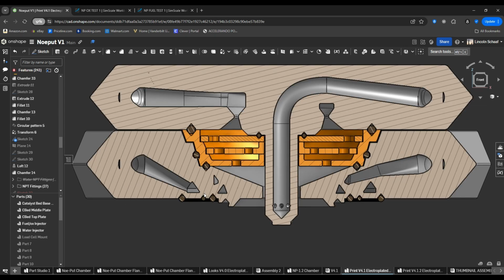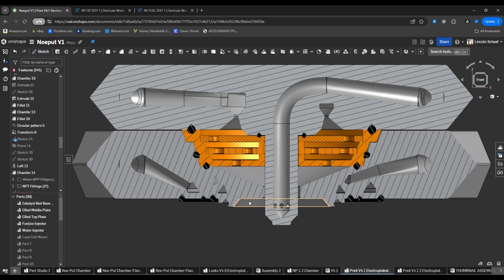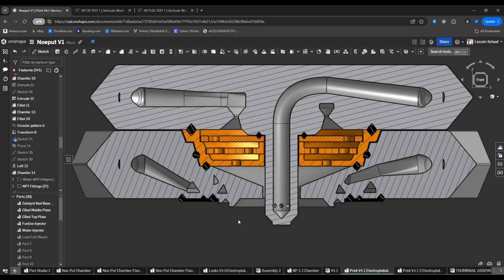So after determining what kind of injector we wanted to use, we used simulations and calculations to determine the size of the injector. So for calculations, we looked at the chamber pressure, which is 12 bar, and the mass flow rate. To prevent backflow of the engine, in which hot combustion gases would go into the injector and potentially through the plumbing into our tanks, which would destroy the test stand, we have the injector at 15 bar, 3 bar higher than the combustion chamber.